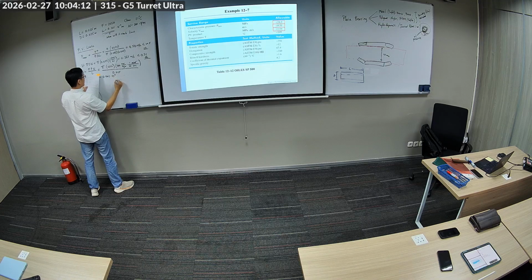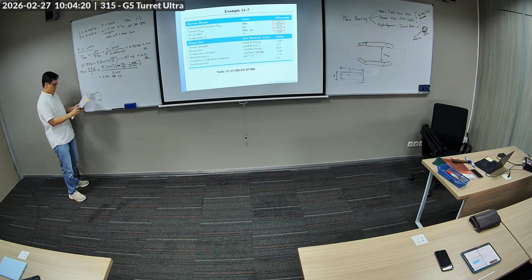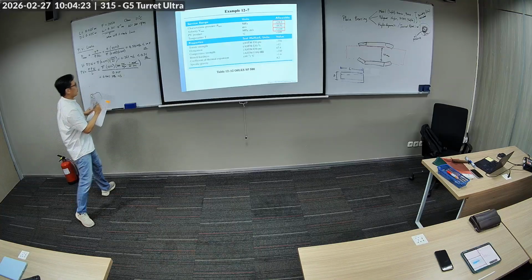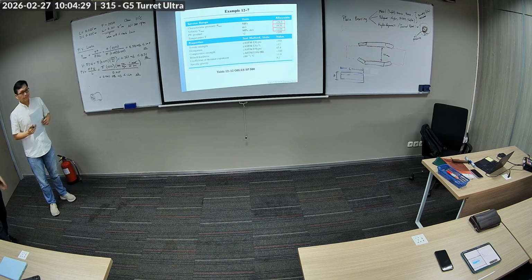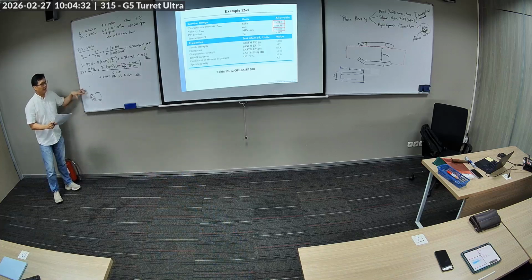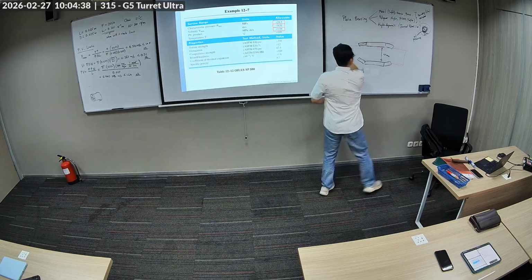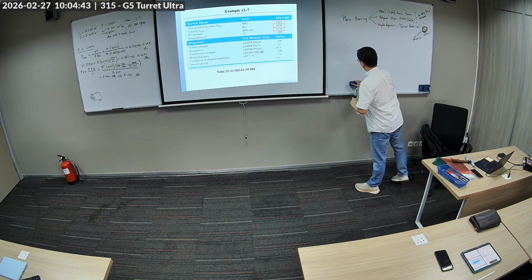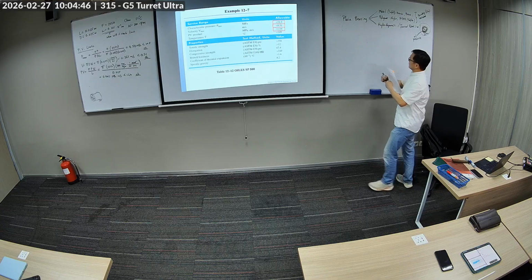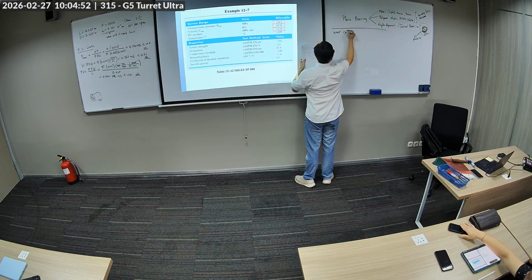Okay? So we have 0.942 times 10 to the 6, or I'll replace it as MPa, meters per second, is the unit of PV. And the limit is 1.64. This is less than 1.64, so this is also okay. Alright, so these are the PV limits that you have to evaluate. Next, we're going to do a wear evaluation. The question is, when will it reach that? So wear calculation.